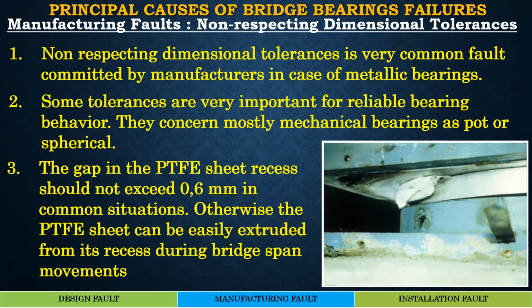Otherwise, the PTFE sheet can be easily extruded from its recess during the bridge span movement, as you can see in this particular sketch. Very important in a bearing sliding element is the proper choice of PTFE sheet, lubricating agent, and respecting roughness limits for the sliding surface and mating element. All that is not covered in great detail in the codes, but I think experienced vendors and experienced inspectors of bridge bearings would know. Many times, due to lack of dimples in the PTFE sheet, and additionally the use of silicone oil in place of silicone grease, the frictional resistance can be as high as 10 times more than the case of properly chosen material, which can lead to failure.